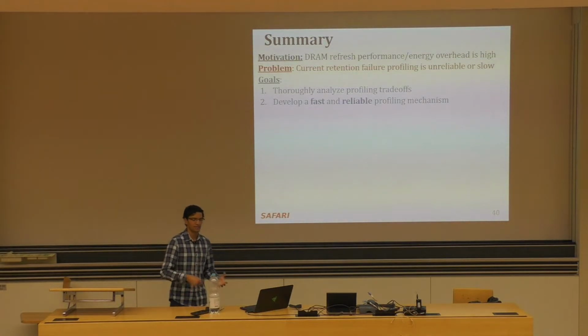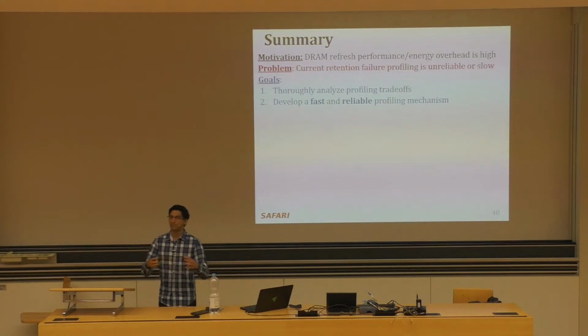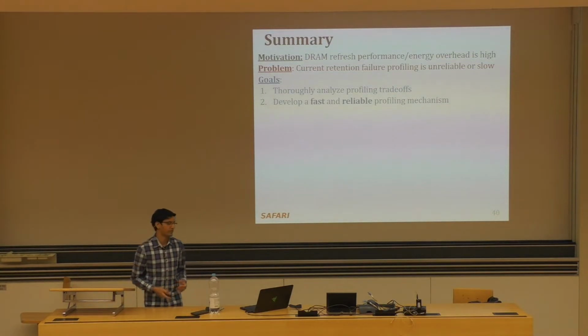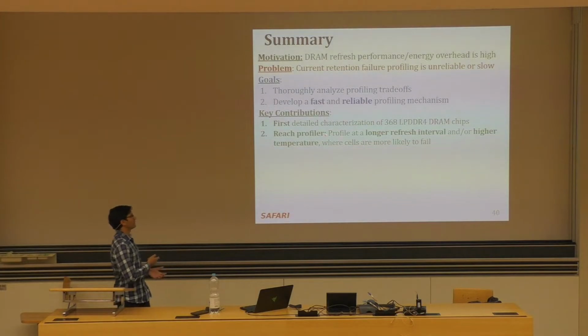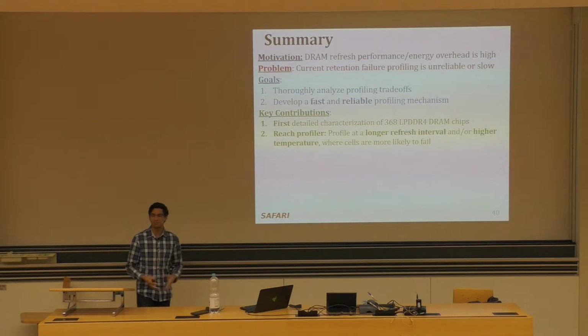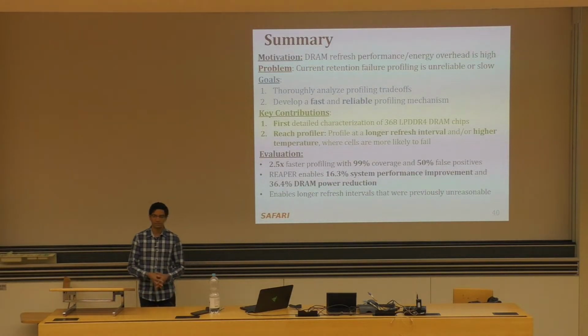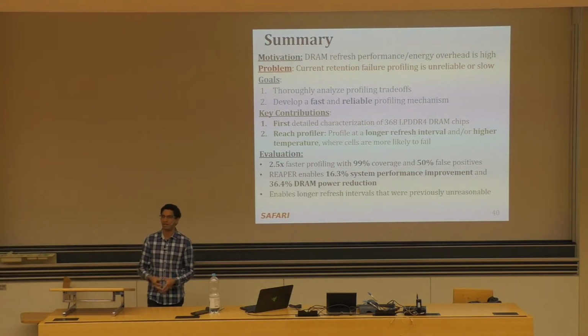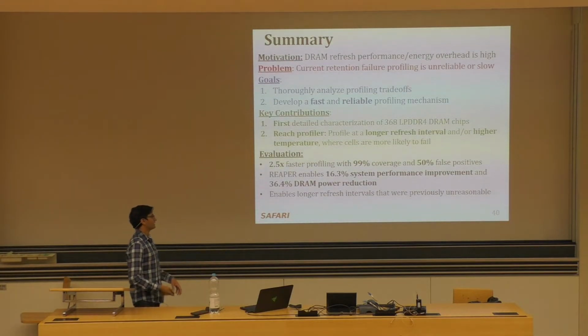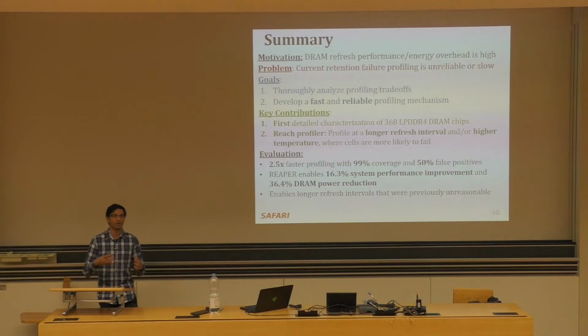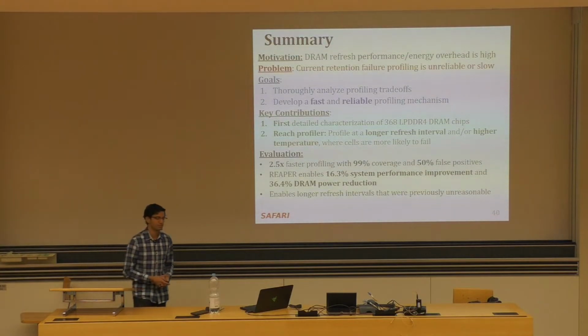And so the goals of this work were to analyze the trade-offs in profiling and then develop a good profiling mechanism based on what we learn. And that's exactly what we do. We perform the first detailed characterization of many different LPDDR4 devices, and we use that to propose the reach profiler. Through our evaluations, we find that the reach profiler achieves a significant profiling speedup at a power consumption improvement, and it actually enables longer refresh intervals that are unreasonable with previous approaches.